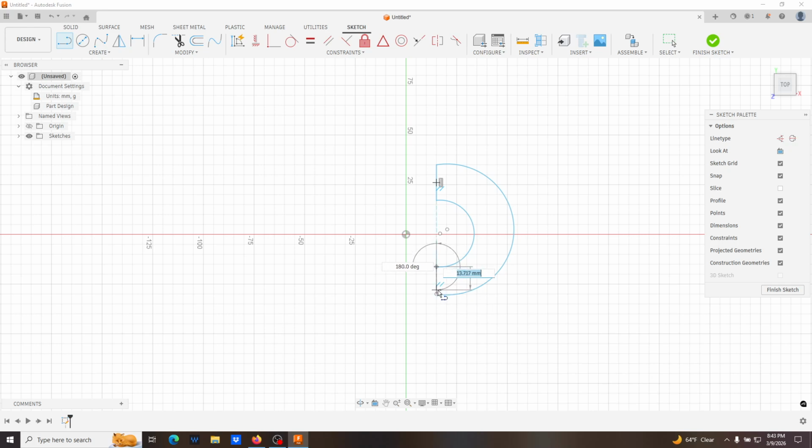And then now one thing here is you'll see that it'll give me an automatic perpendicular constraint. I like auto constraints, but sometimes I want to turn them off, because you want to be careful with them, because sometimes you'll put in relations that you don't mean to. So what I'm actually going to do now is just draw this over here and then press escape, and then I'm going to select these two points and then go from that. And then I'll put a coincident constraint here. So one of the things about auto constraints is that, especially stuff like that, sometimes it'll be trying to help you out, but it'll kind of get in the way. And in this particular instance, I didn't want that to be parallel.